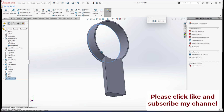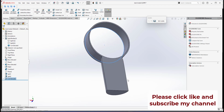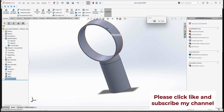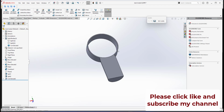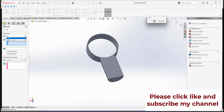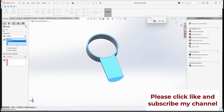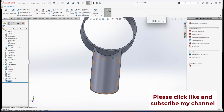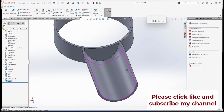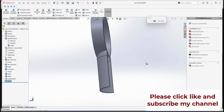Right, if you look at the back here, this is the handle. The handle is not supposed to be solid, so I will make a shell of thickness 2, the same thickness that I've just created for this cutout. To do that I will do shell, so I will give a thickness of 2. Then I select this face and this face. Now I have hollow thickness for the handle. Now the handle is already hollow and the thickness is 2.